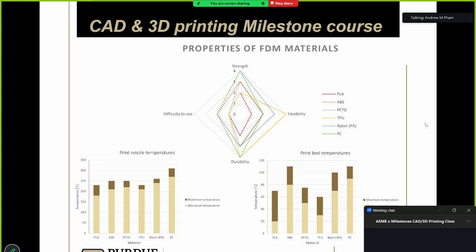In the past, some people would use specific support filament made of PVA, which is basically the same kind of material you'll find in a glue stick. So people will print a very complex model with one material and then the supports out of PVA, and then they'll soak the model in warm water afterwards, and the supports will just dissolve off.